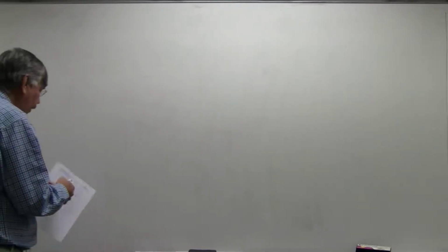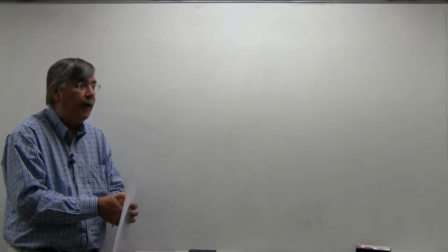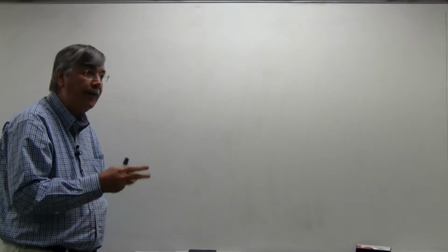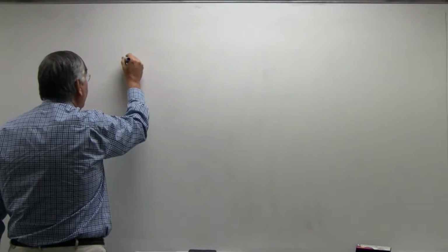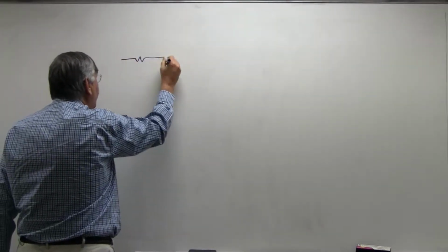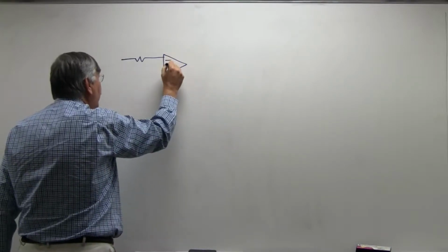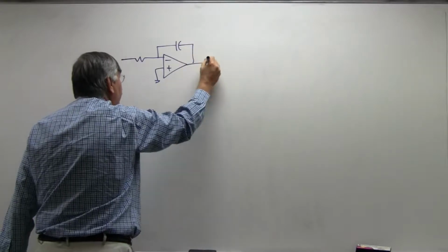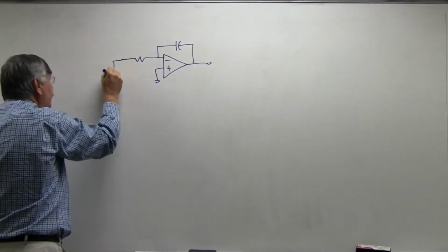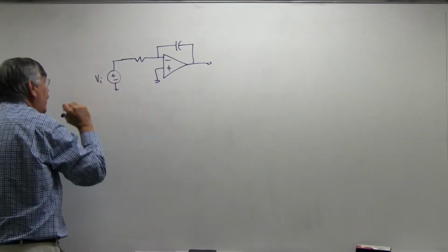show you some tricks here, and now I'm talking circuits, so I'm really on my most familiar ground here. The basic circuit element that is at the heart of every filter, we can start really with first order filters. If I wanted to start a first order filter, I can use an ideal op amp, or maybe a real op amp, in a configuration like this. Now this circuit is an integrator, and most of you probably know that from some class that you've taken.